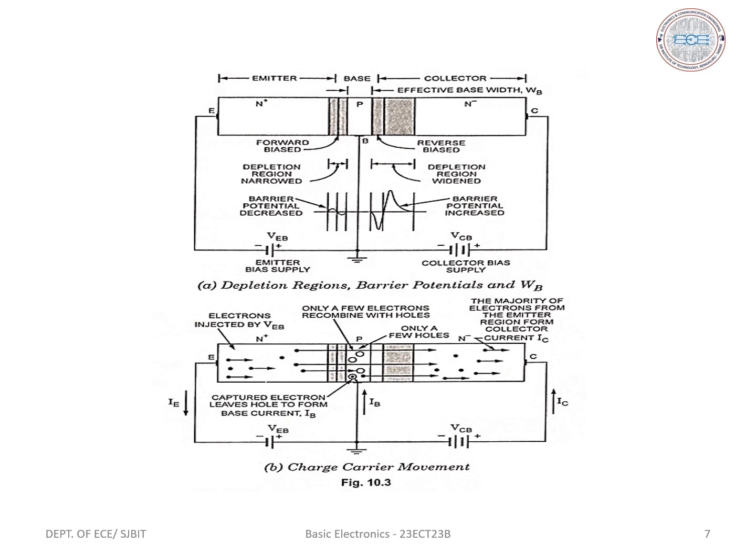The base emitter junction of the transistor is forward biased by applying a voltage VBE as shown in the figure. The width of the depletion region at this junction therefore reduces. The supply voltage VCC will make the collector base junction reverse biased. This will increase the width of the depletion region at the collector base junction.